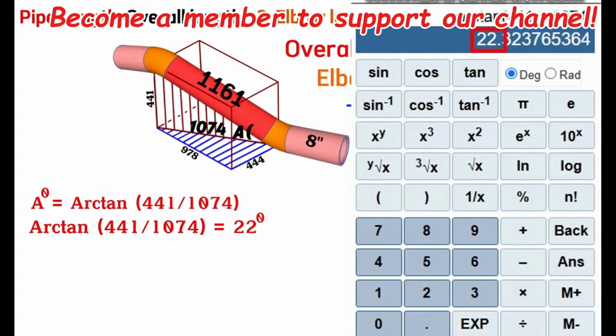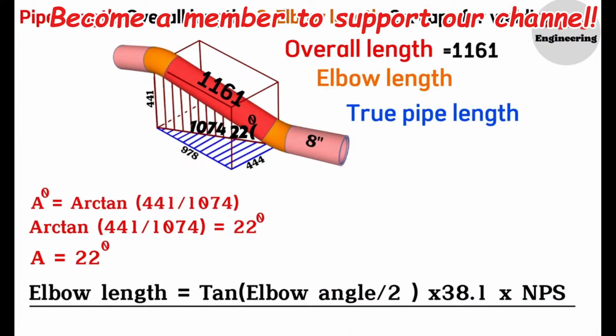Now we should find the length of the 8-inch 22-degree elbows. We will use this formula to find the length of the elbow, which we have prepared and shared in many videos previously. I will also include the links to those videos in the description below. The elbow length will equal the tangent of the elbow angle divided by 2, times 38.1, times the nominal pipe size (NPS) of the elbow. Now we will substitute our elbow angle and nominal pipe size information into this formula.